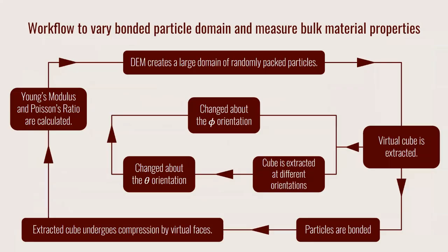My research methodology starts by randomly packing particles in a large domain that have been compressed to a desired packing efficiency, which is achieved in LAMMPS. LAMMPS is a DEM and molecular dynamics package developed by Sandia. Once the domain has been created, a smaller virtual cube is extracted, and each discrete particle in the cube is bonded within LAMMPS. Each extracted virtual cube is then compressed along one set of opposing cube faces.